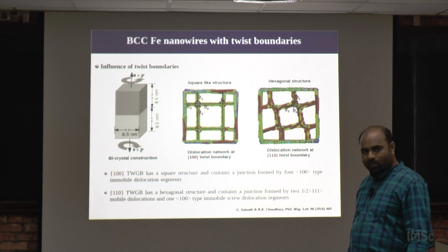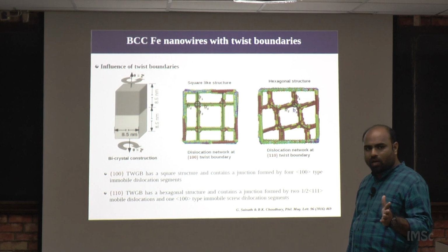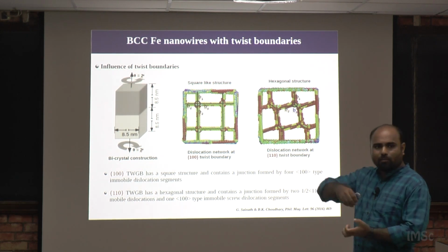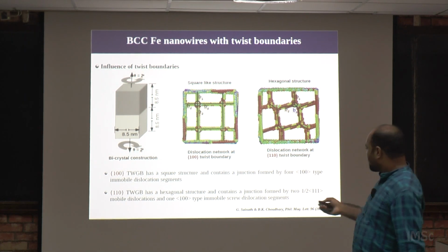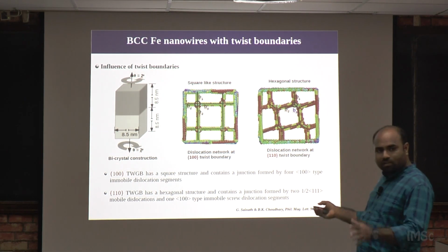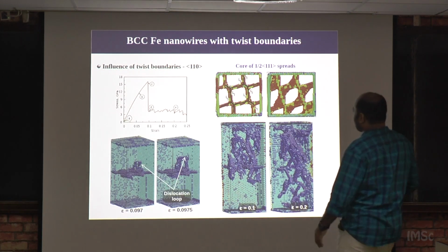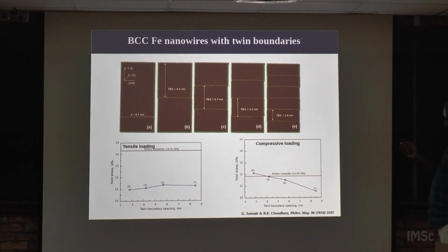Yes. Actually, not continuous, that is the twisting itself, that is one kind of deformation. We have first twisted and then applied a tensile load. The twisting is basically to get some kind of dislocations, that is the purpose. And then apart from that dislocation, we want to do some kind of a typical grain boundary. So, this is a twist grain, twin boundary or sigma 3 boundary, and with respect to spacing, you